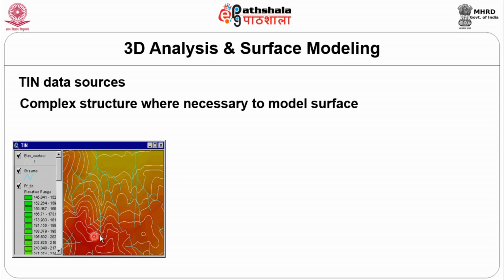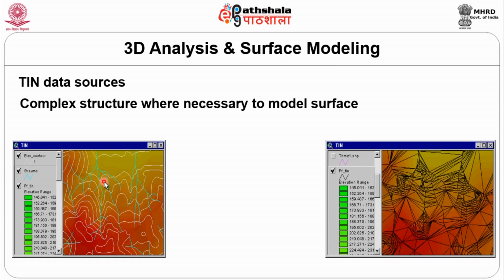You also have the contours and also the drainages which are running across. So, this sort of a thing has two different aspects, namely the contour and your drainage system. If you want to visualize the flow of water, for example, then this sort of a model will be very important, because here you know the z value through the contour part of it. Create that TIN, because you can just convert these lines into point data, or you can use the lines themselves as input. Create the TIN, and then once you create it, as I was telling you, incorporate or superimpose your drainage map over that and analyze. So, in that sort of a case you require that.